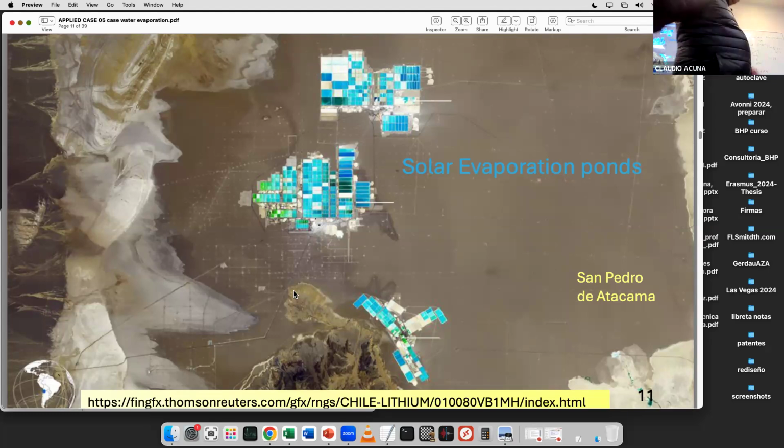But let's say here in a swimming pool, how much is an evaporation rate typically for water? You want to evaluate how much water you are losing? Evaporation rate. Number, engineers. 10 liters per square meter daily. It's a standard evaporation rate. If I have this one with water, I can determine how fast it's evaporating, just knowing the dimension.